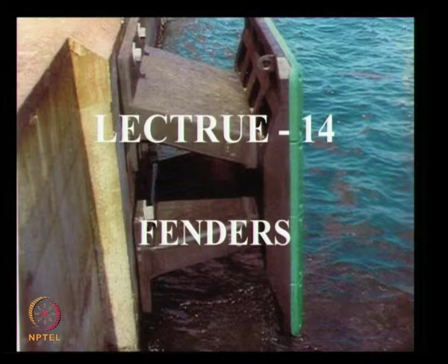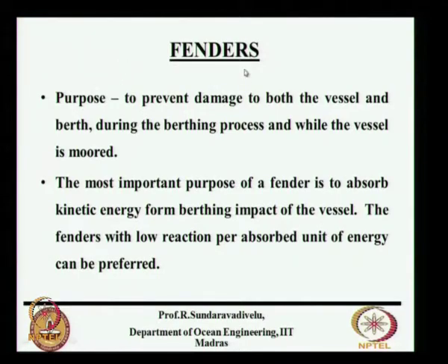So, you have a special design requirement at this place where we are fixing the fender to the structure. What is the purpose of a fender? This is to prevent damage to both the vessel and berth during the berthing process and while the vessel is moored. That is two operations. One is when the vessel comes and berths, second is when the vessel is moored.